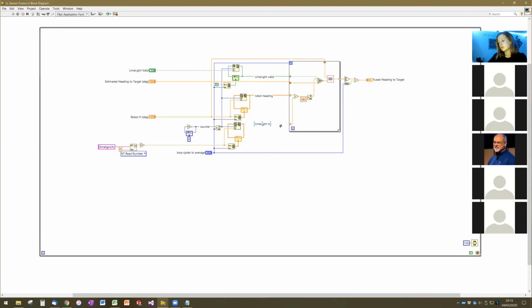The problem is that these 3 arrays, as the robot was turned on for longer, the list was getting longer and longer and longer. We were adding 3 numbers every 20 milliseconds for the entire length of time the robot was on. This is eventually going to fill up the memory on the robot. I don't know that this is one of the reasons that we had some weird instabilities when we left the robot on for long periods of time, but it is possible that this was causing a problem like that. So we need to make sure we make that change to the code. Does that bug make sense to everyone and what the issues are?